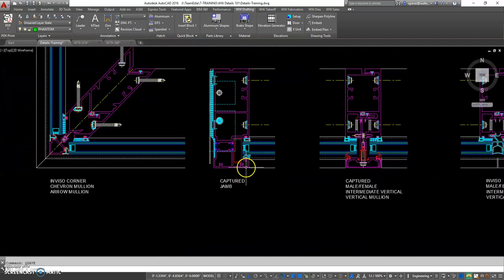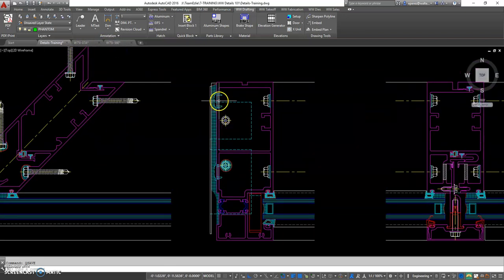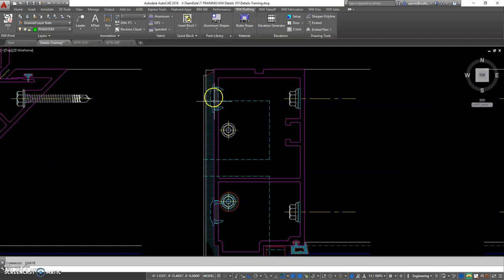Okay, so those are assembly screws. In order to use the assembly screws and attach the horizontal pieces to the verticals, we need to have access. So we need access holes. So on the jambs, we have these access holes shown with a notch, and then we plug them with a silicone plug to help hide the holes as well as plug it so no air comes through after the screws get installed.